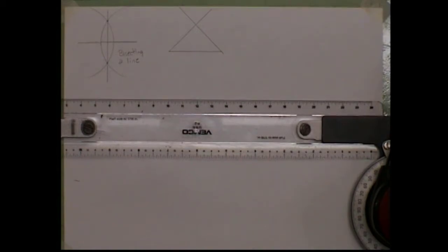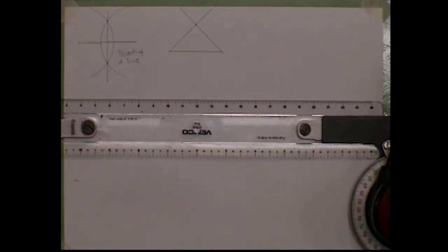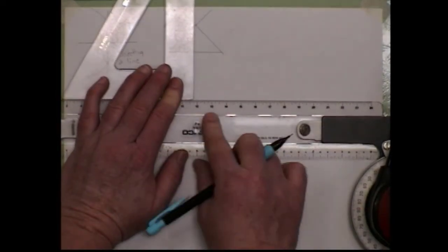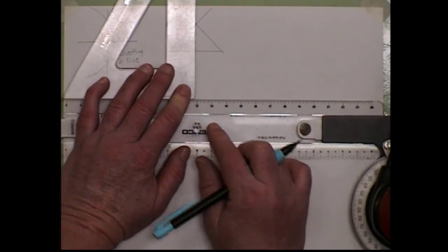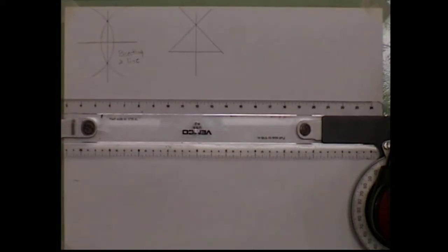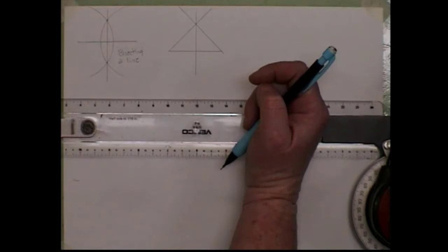And where they meet at the top, I have this point. Now I don't have another point at the bottom. I could do it. I can flip my triangle over and do it at the bottom, but I don't need to because now I can take a straight edge, make it flush with my horizontal edge, and make it tangent to that point. And now I have bisected that line using my 45-degree triangle. I still didn't measure anything, but I used the 45-degree angle to my advantage and found the midpoint and just made my line straight down.